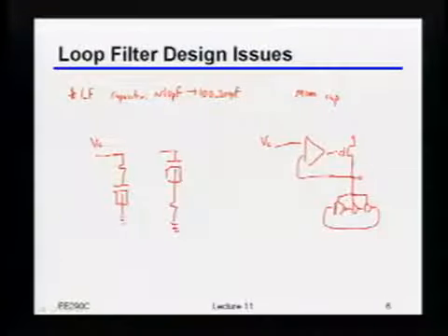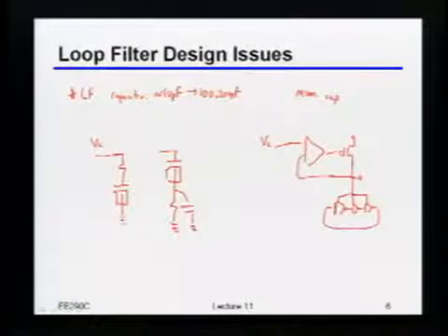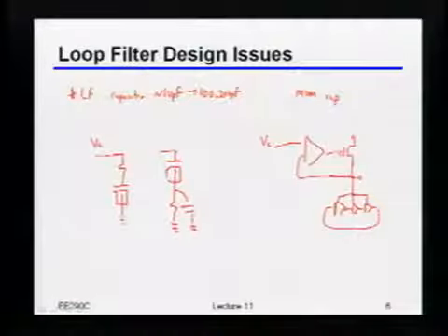You have a lot of ground capacitance. Yeah, I have bottom plate, right? So on this one, I have a bottom plate cap that sits right there. What's bad about that bottom plate cap? What does it do to you? That's one more pole. Say that again? That's a pole. Yeah, it adds a pole, right?